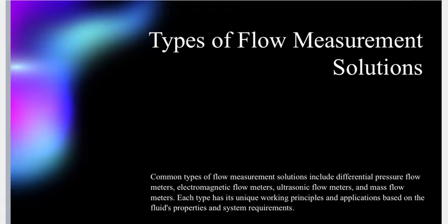So the common types of flow measurement solutions include differential pressure flow. What does differential pressure flow mean? It works based on the Bernoulli principle. You will know it, we are studying that principle in our thermodynamics subject. That's why we use differential pressure.